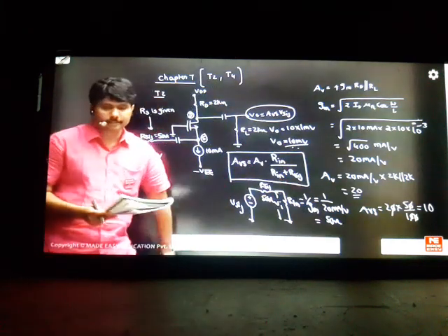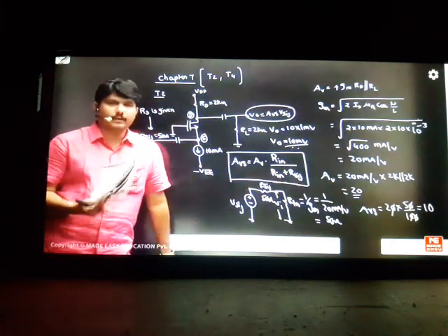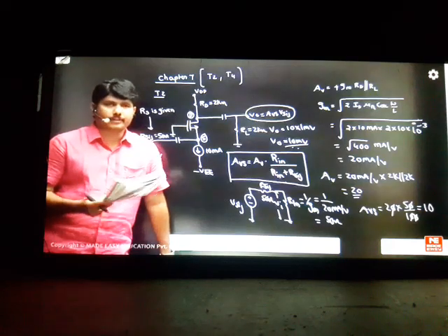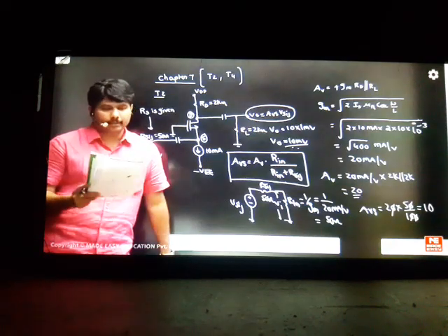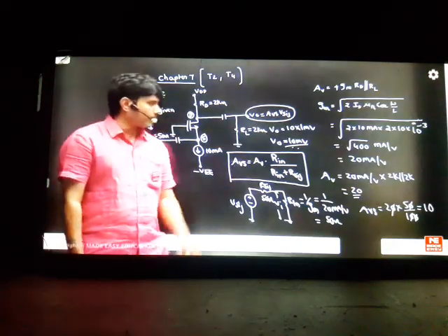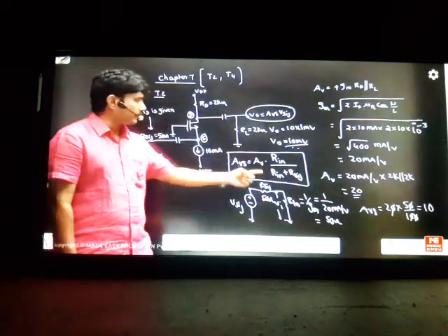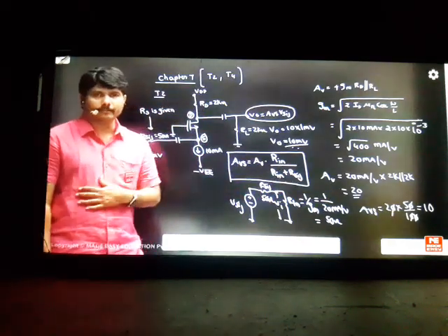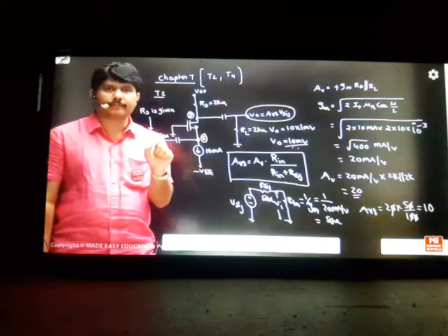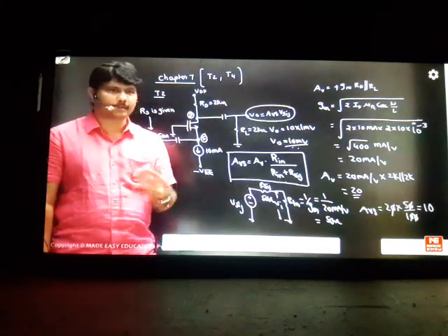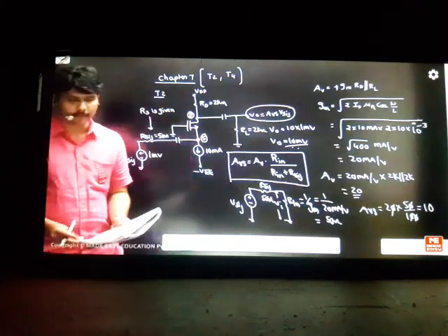Very interesting questions. These questions you practice. So 10 millivolts. First of all, we will have subject knowledge. Option A, option B, they'll say wrong because minus never comes because they are not phase shift amplifiers. Only option C, option D will be correct, that I found in the class. Some students will write the answer as 20 millivolts because they forget that R signal is given. We have to take some attenuation factor. If you leave that one, then a mistake will happen in the problem. So whenever RS is given, the transistor gain formula and the circuit gain formula will not be the same. If you want the overall gain, you have to take this ratio always. Okay? It's a very good problem.